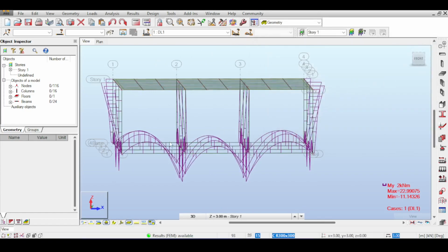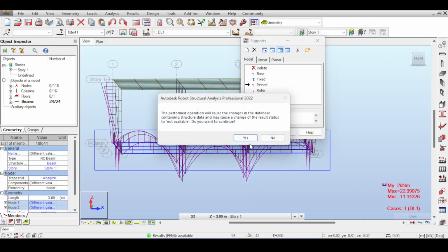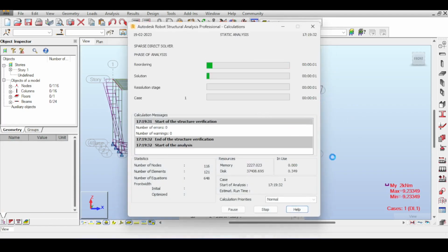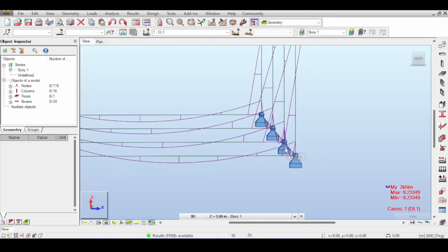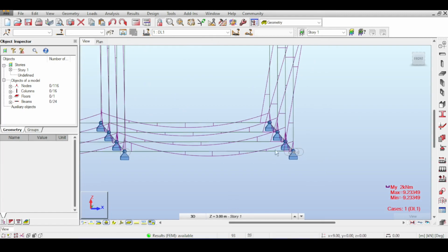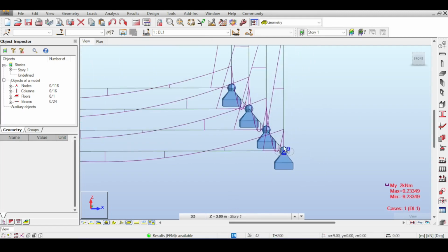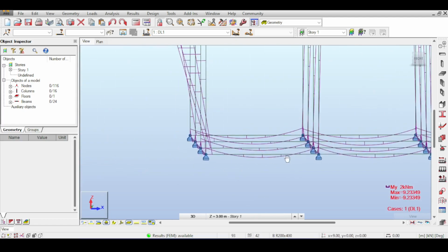Now, first things first, I have instabilities. I ignored that. I will tell you why in a moment. Let me recap now. First of all, let's add back the pins. Now, if you have the pins, then you would have a strange simply supported beam because you added pins, but there is still the continuous rigid connection between the column and the beam, which will in turn transfer the moment of the column onto the beam, and that's why you have this strange odd diagram.